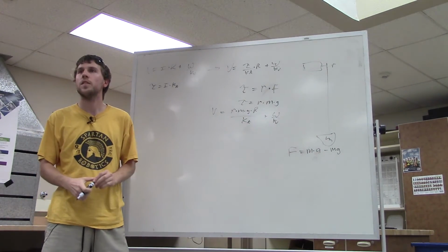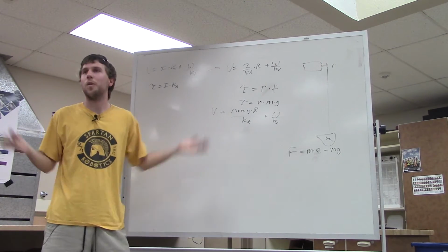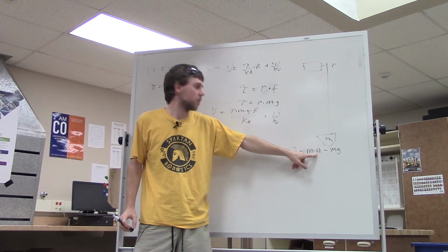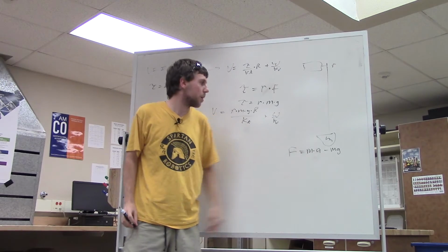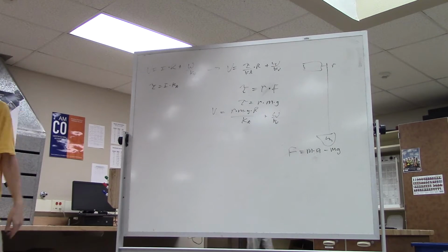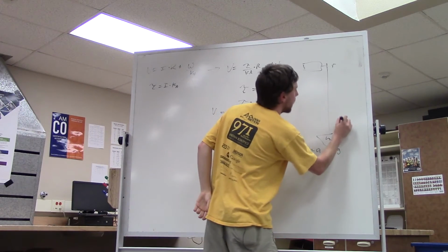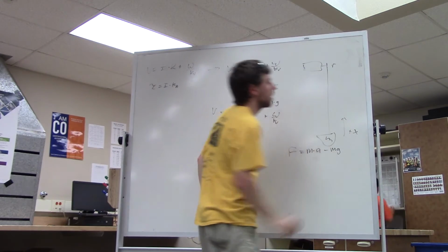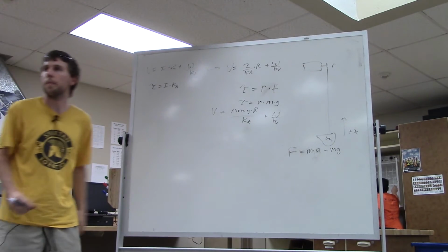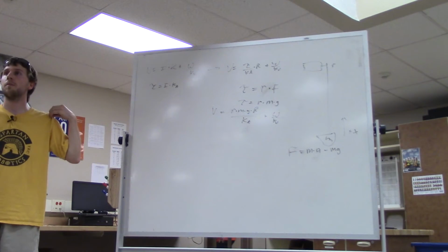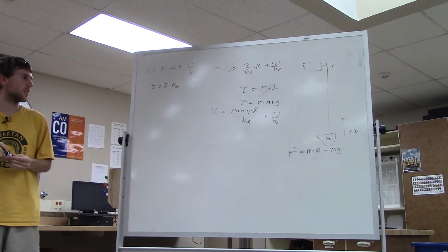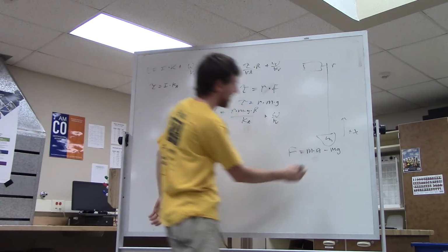Why are we subtracting mass? Are we lowering this object or raising it? We don't know yet. Then why are we subtracting the force of gravity if we don't know which direction we're going in? Gravity's always pointing down. So we just need to find a coordinate system, which is the next step. So we want to say plus x is in that direction, right? Since we're essentially trying to find a tension force, wouldn't it be additive? You're right. Good call. Thank you.